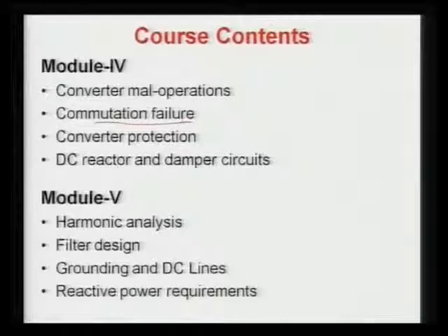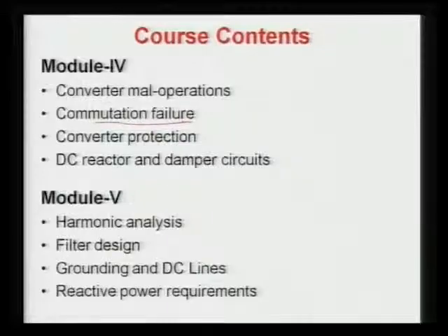The commutation failure, which occurs only on the inverter side, is a very frequent phenomenon. It is discussed again in detail for single commutation failure and double commutation failure. Single commutation failure means only one commutation failure in one cycle. If it happens more than once, it is called multiple commutation failure. In this module the first and second commutation failures are discussed, and we will see what the output voltages will be and what the impact on the valve voltages will be.